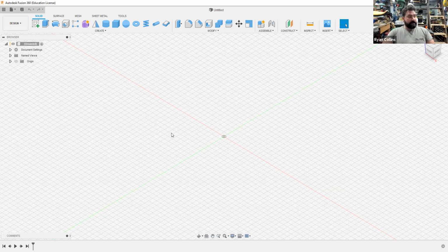The other aspect you want to see is up here in the upper right-hand corner. This is your view cube. This shows you how you are viewing your environment. Now, if you've ever worked with any other 3D modeling programs, any CAD programs, you're probably used to seeing the 4 different views rather than just this big perspective view. You can change that. Down at the center of the screen at the bottom, you'll see these different options. You have orbit, look at, pan, zoom in and out, fit.